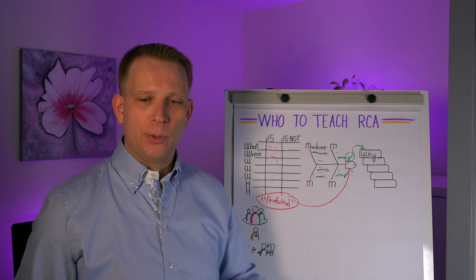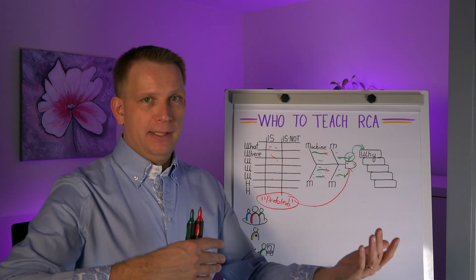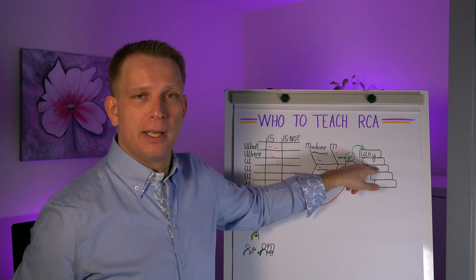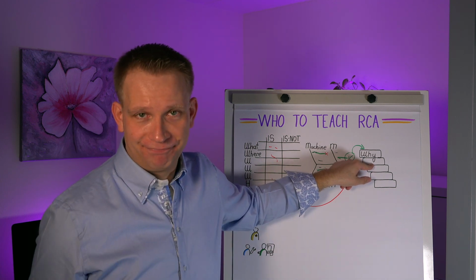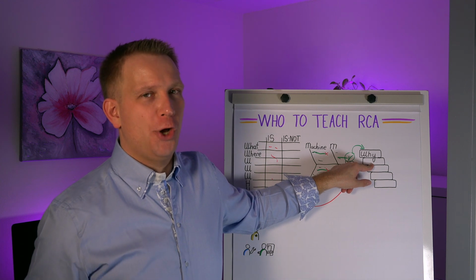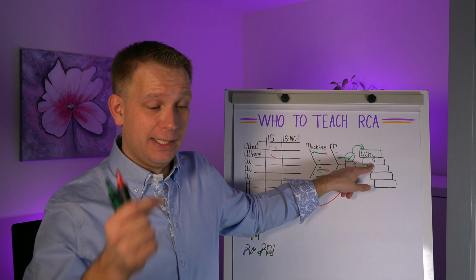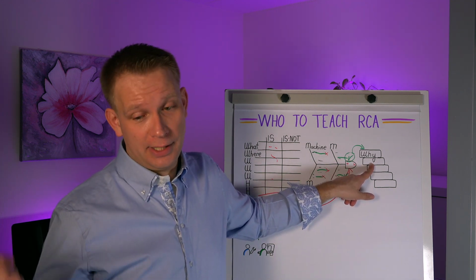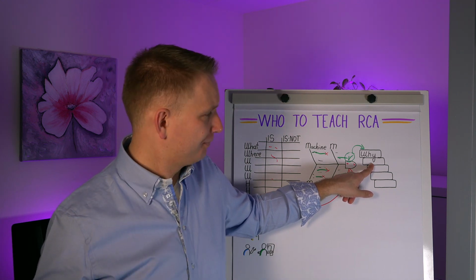But why did the gear wheels break? Well, they broke because there's too much tension, misalignment of an axle. We're somewhere here, right? We have got to get that axle aligned again. That is fixing a root cause. Now, if you can get this into your organization's thinking, that at least they're aligning axles instead of only fixing the gear wheels and then next week fix it again, you have already won a lot.